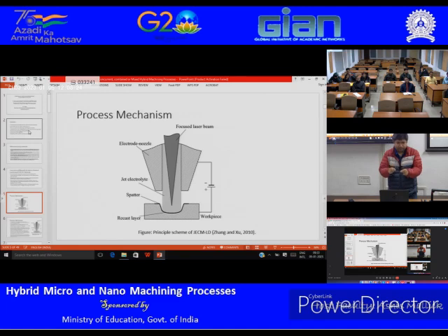That means the heat affected zone and recast layer are removed continuously. So the whole diameter that you will get is more relevant to the electrochemical jet diameter. The laser is making the pilot hole mostly, so the electrochemical jet diameter will control the diameter of the final hole.